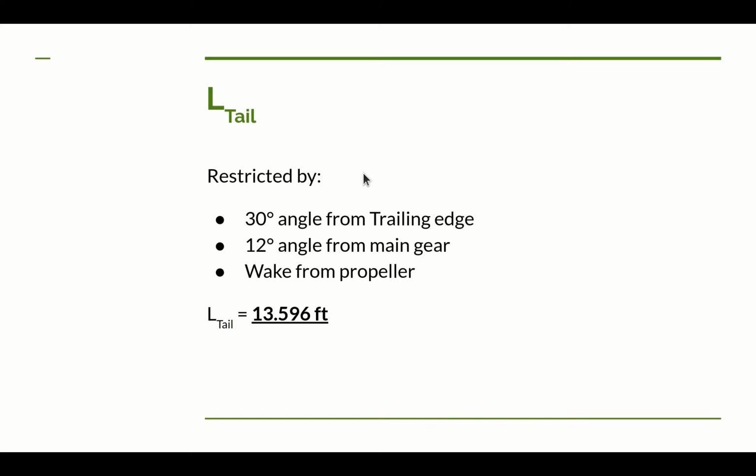Now, one thing that helps a little bit here for this airplane, if I'm going to use that V-tail, is I only have to have one length number, while horizontal and vertical are the same thing. So really all I need to figure out now is what is that length for my V-tail. So now we can get into determining what that length is with a few other helpful criteria or restrictions.